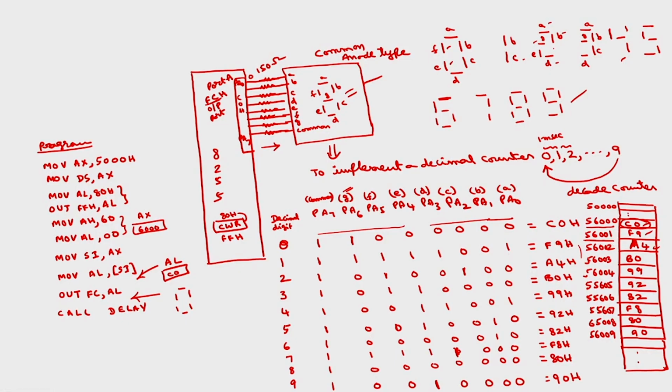So you have to just simply increment AL, INC AL, compare AL with 09. So up to 09 we have to increment this. We will compare with 0A, because 9 also you have to display, right. So you take one above this, 0A, jump not equal, up. For 0 with 0A if you compare, it will be not equal.